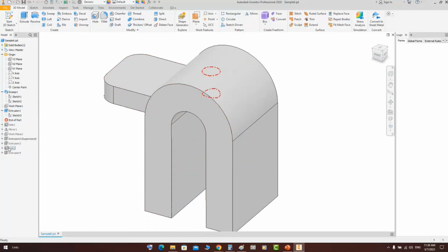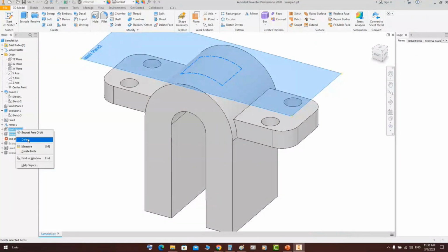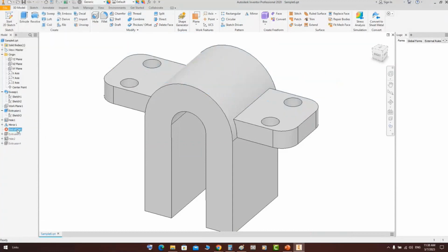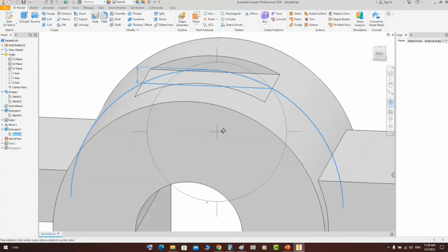After that, we create this wing including the fillets on the sketch itself. After that, making the holes, making a mirror for this wing and the holes, create a work plane and create this cut. After that, we freeze it so we can delete them. Okay. Here we make another way to make this cut by creating a sketch here with a depth of 4 millimeters.